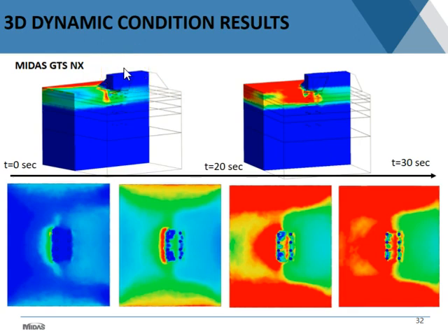Which typically reduces the demand on the bridge. Because if you have a certain amount of displacement in the longitudinal direction, and the soil sees the opportunity to not only push the bridge but also go sideways, a portion of the soil is going to do that, and that's something that is going to be shown in a figure that is coming up.